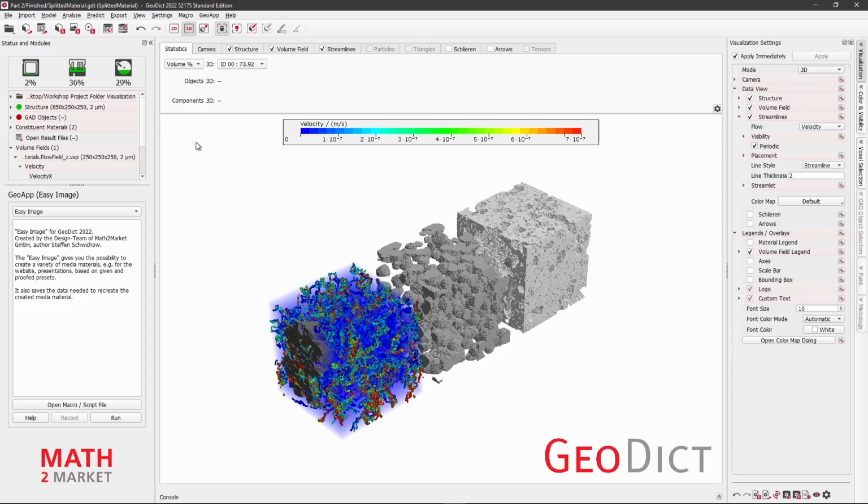To account for the fact that the filter gradually clogs over time, FilterDict lifetime uses an iterative approach. First, a flow field is simulated for the clean filter medium, then a so-called batch, a subset of the simulated particles, is injected into the filter medium. Then, for the partially clogged filter medium, the flow field gets recomputed and the next batch of particles will be injected. This process is what we are going to visualize here.